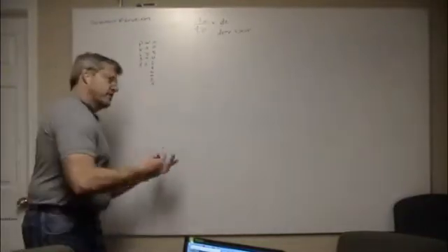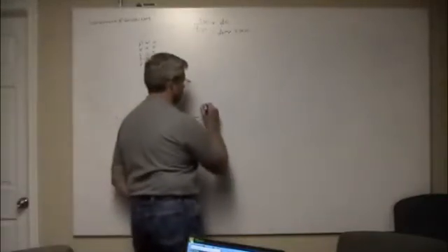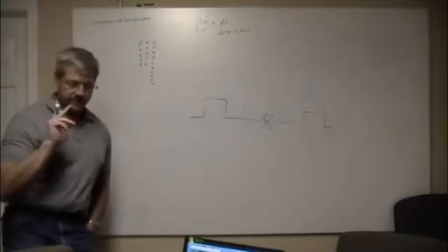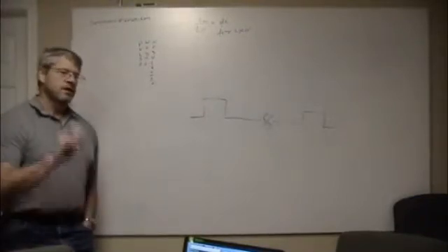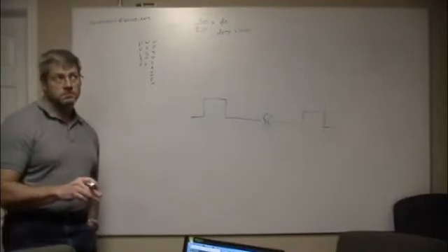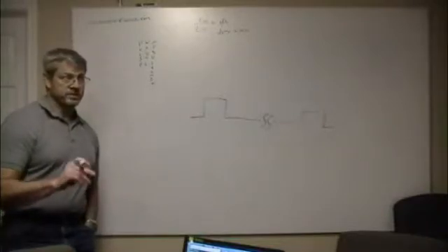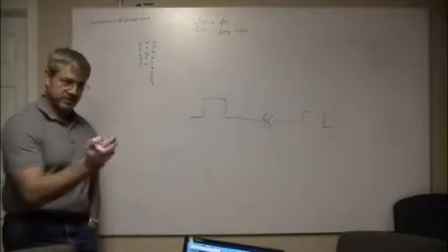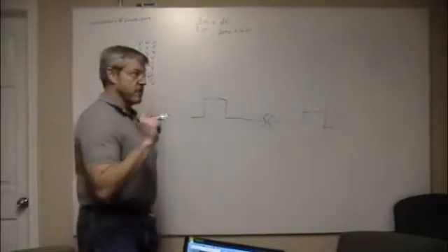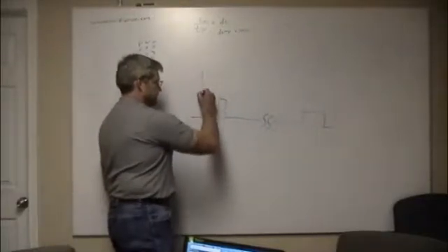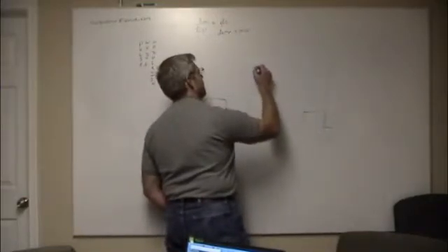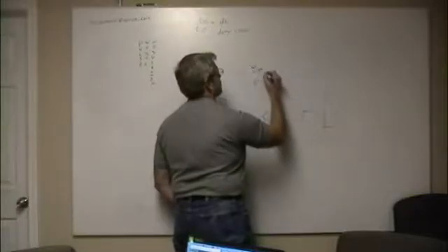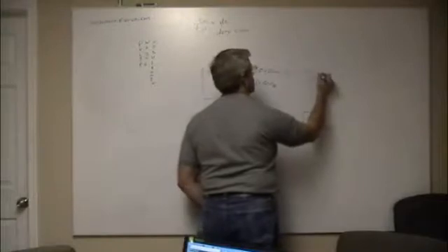But why am I going into this? The way you control most servo motors is with a PWM. That may be a lie. Every servo motor I've ever used or built around uses a PWM control. I don't know about what's used in a CNC or something like that, but for remote control cars and remote control airplanes, little servos in there, this is how they work. They're not all this signal, but they seem to mostly be this signal. The frequency is 50 hertz, which is 20 milliseconds.